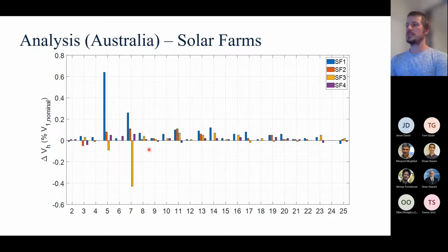So we did similar analysis for a bunch of solar farms of varying sizes, connection locations, topologies, even voltage levels, all sorts of things. And what we find is that solar farm 1 has ultimately the biggest impact, and the size of that solar farm from memory was actually the smallest. I think solar farms 1, 2, 3, 4 go up in nominal ratings. The impacts that we actually measured were either quite minimal or actually attenuating your voltage levels. Again, very high level, very simple and statistical, long-term probabilistic impacts. But what we're not seeing is that substantial jump in distortion levels as soon as things connect.